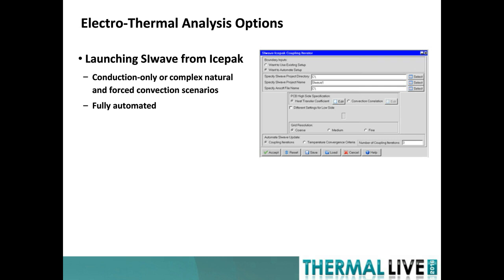Now, once that ECAD file is in, it describes the complete geometry of the traces and the layer stack up and everything. Once that's in IcePack, IcePack computes the detailed metal fraction from that ECAD file, and it's that metal fraction that IcePack uses for the CFD simulation. So it takes the ECAD file, which describes the geometry and exact detail in the board, and computes a metal fraction. And then that metal fraction is used in the CFD analysis. And similarly for mechanical.